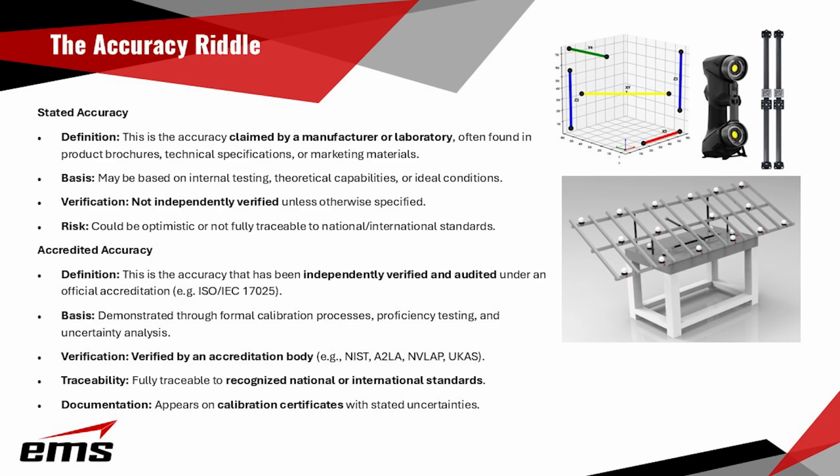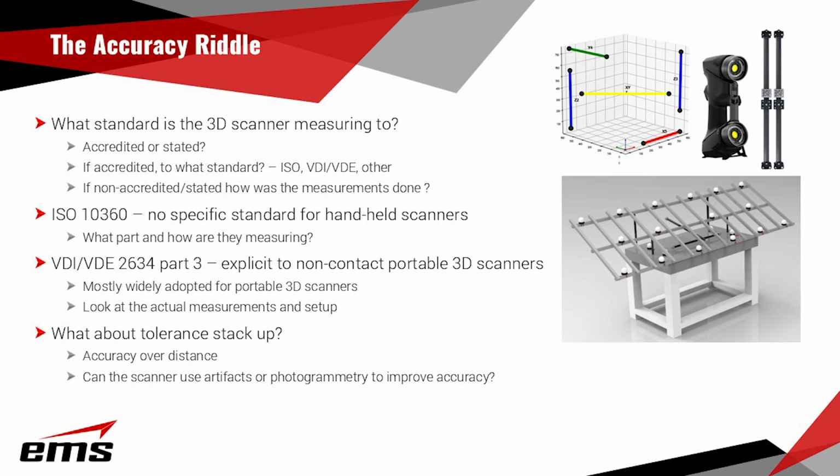What accredited standard are you referencing? And again, if it's not accredited or just stated, then to what, right? And that also goes back to the ISO 17025. If it is just a stated accuracy and they are not an accredited lab, I just wouldn't hold a lot of value in any statements they're putting out there, because you just don't know unless they're willing to share in detail how it's being done.